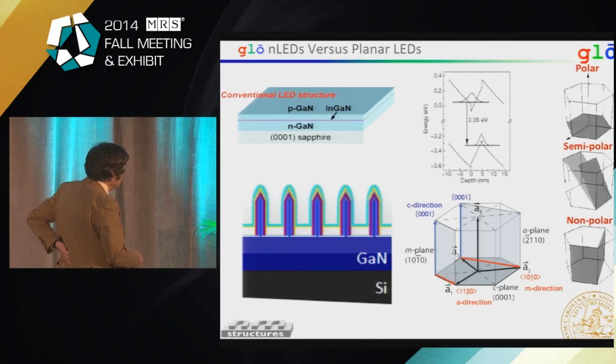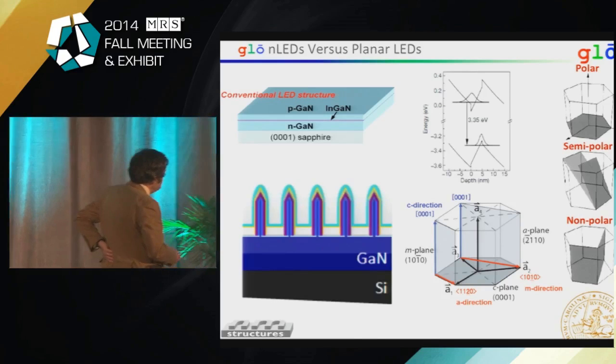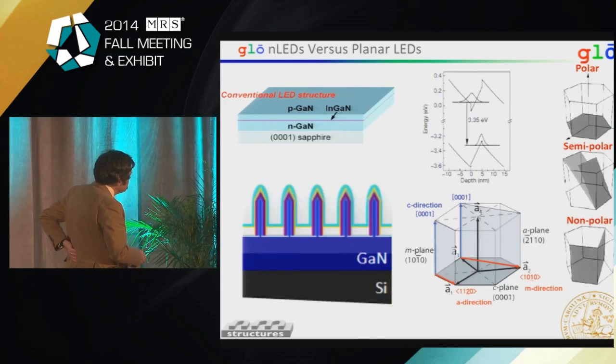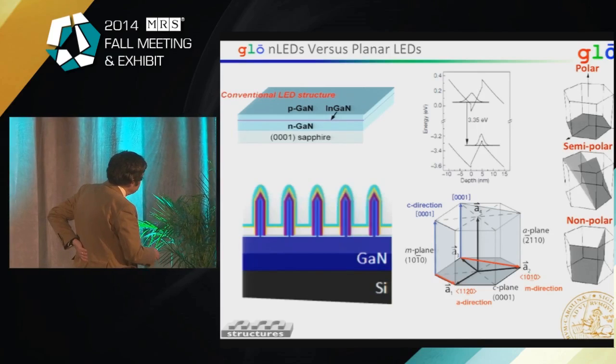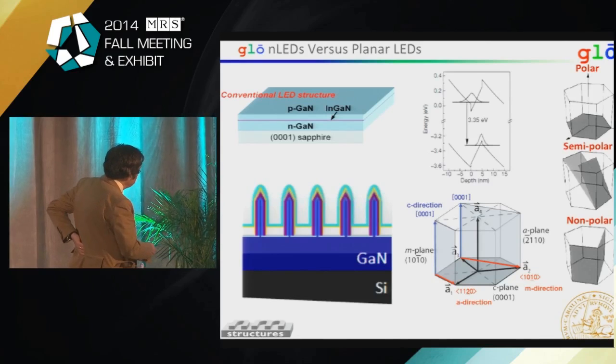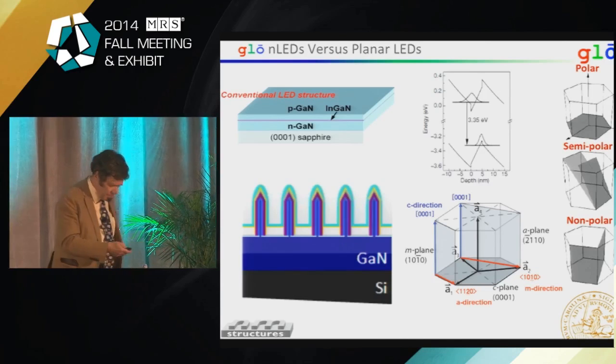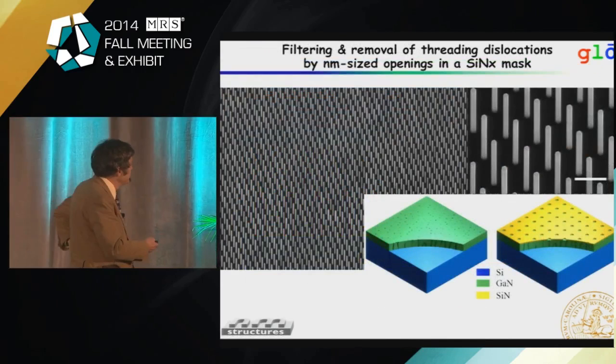And we do this in two steps. First, on the gallium nitride with all these 10^8, 10^9 dislocations per square centimeter, we put a thin growth mask of silicon nitride. And then we make small openings around 100 nanometers or so. And we grow the seeds of defect-free gallium nitride nanorods. And then we switch growth mode and we do the whole device in the radial direction. Maybe that was cryptic, maybe it will be clearer in the next slide.